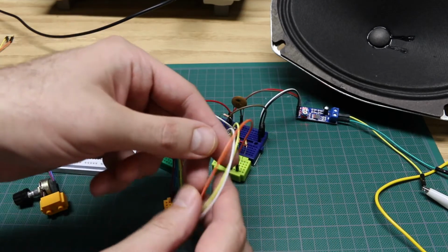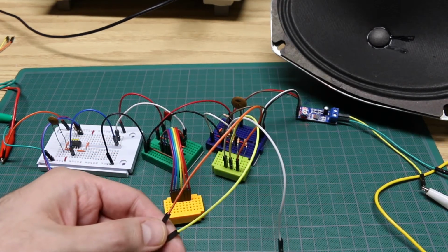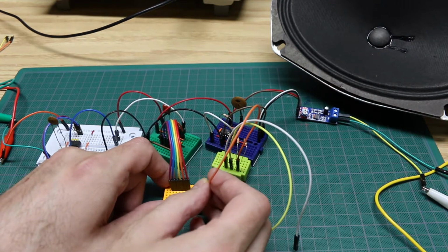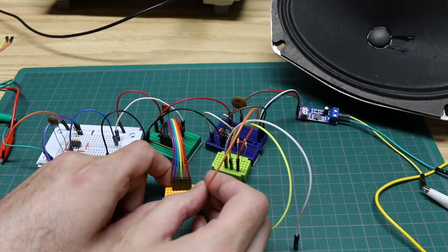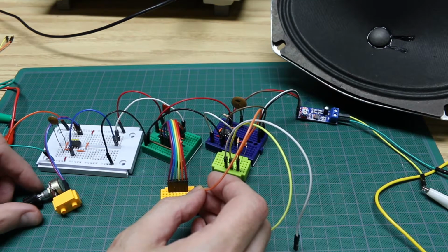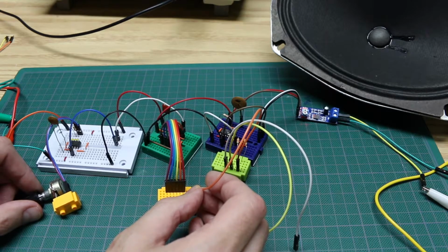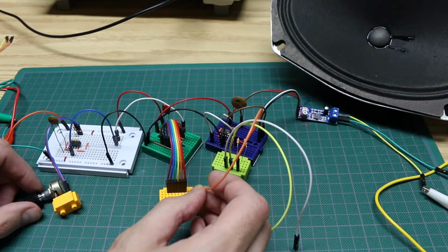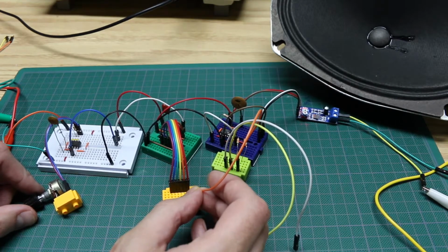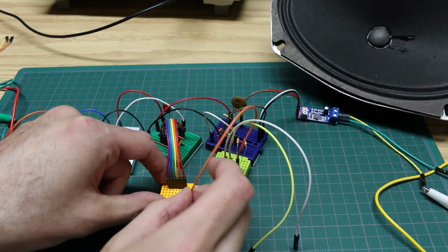Here's my 3 channels of the mixer. It doesn't matter which is which, they're all just waiting for an input. So the highest pitch we're going to get is going to be the main 555 clock signal. And I just arbitrarily chose values I had around, so it doesn't go as low as I would like normally for an oscillator, but we're dividing it down anyway, so it's going to just go down to clicks eventually anyway. So here's how the main clock sounds.